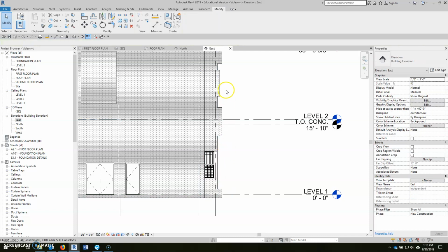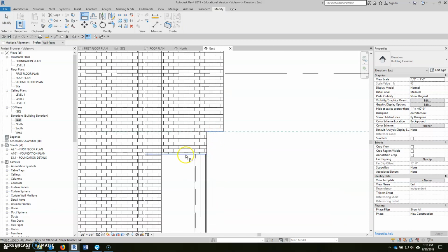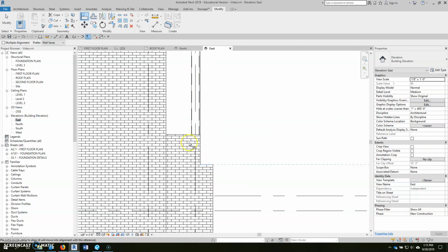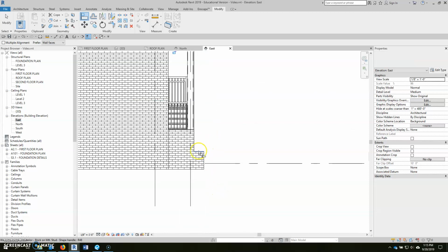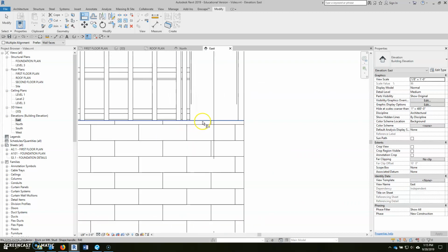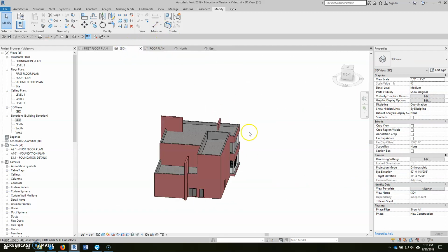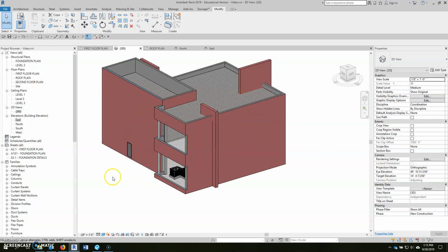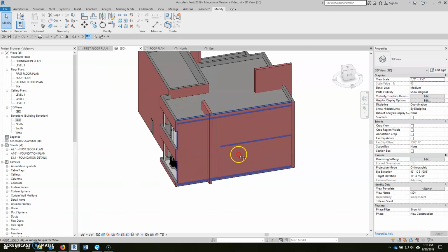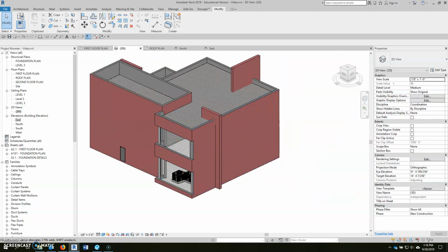And now I can select that wall and that wall. And again, that align tool, it's a lifesaver. We can use that and align to that wall, the top of this wall, so on and so forth. And very quickly, and sometimes you've got to zoom in to get the right line, we've split this wall up the way we need to. We look again at a 3D view, and that curtain wall, or what will eventually become curtain wall, wraps around. I'm going to go around to this side of the building, doing the same exact thing, and I'll come back when that's finished.